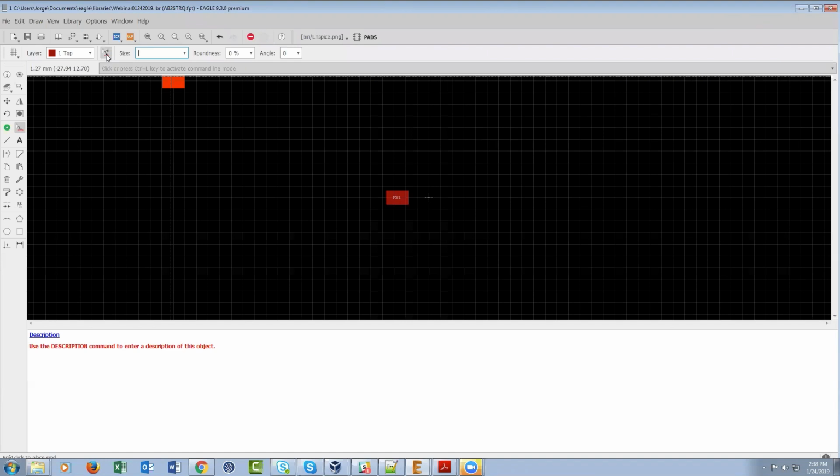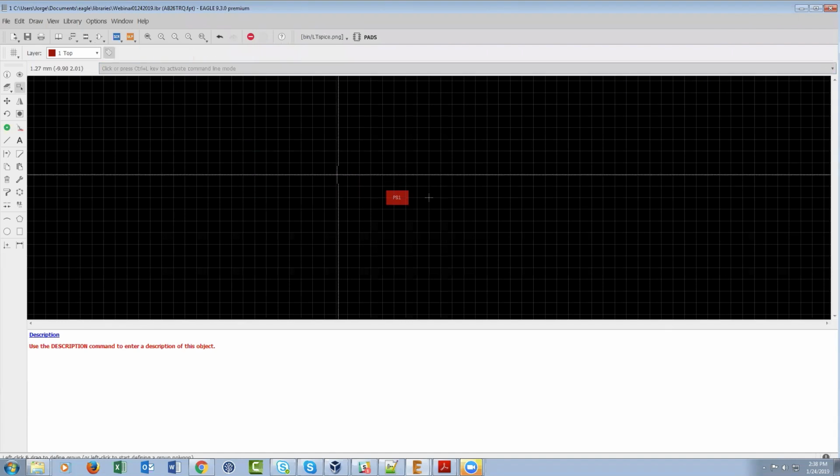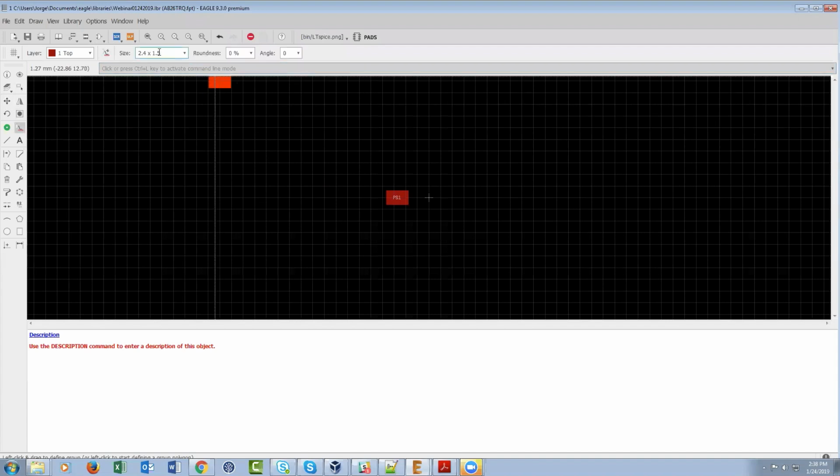When you activate the pin command, you're going to see it there on the parameter toolbar. The very first toolbar you see on the top, we refer to as the action toolbar. The second one below that is called the parameter toolbar. That's the one that changes when you activate commands. When you activate any command, always check that one out because there's always really cool options. I know our experienced users know that one well, but for anybody that's new, always check that one out.